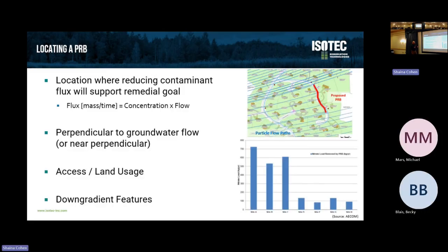This slide here on the bottom, I mentioned nitrate earlier. This was a site, a community on Cape Cod. So this PRB and some of this talk for me, it's coming full circle. PRBs have become a potential tool for removing nitrate when there are large nitrate plumes in places like Cape Cod and Eastern Long Island, where 80% plus or minus of the wastewater is going to septic systems. That has happened over decades and decades, creating large nitrate plumes.